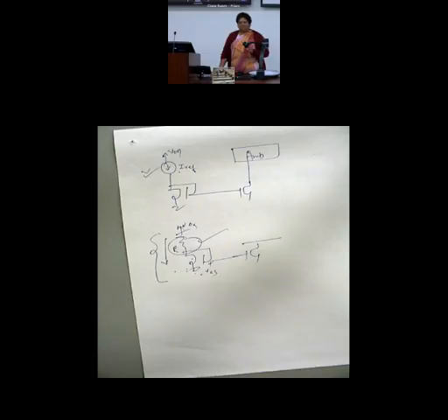Now, if a user does not want a gain of 9 but wants a gain of 10 every time, he will ask the designer to design a circuitry which will give a gain of 10 only, nothing else. So how to guarantee that I bias will not change? That is the only way he can design. This is to be done by making IREF constant.